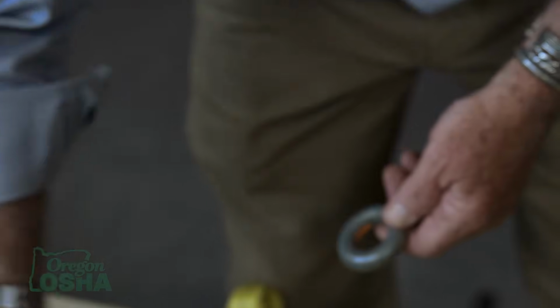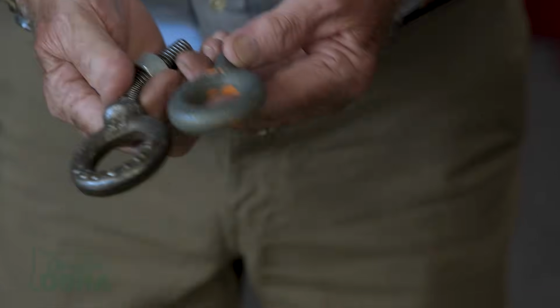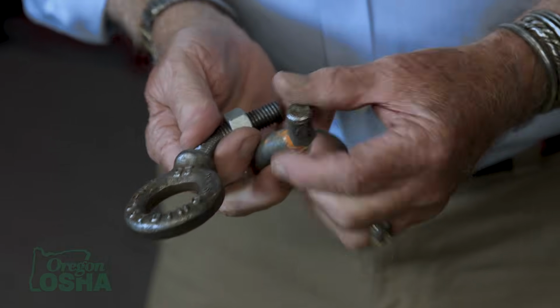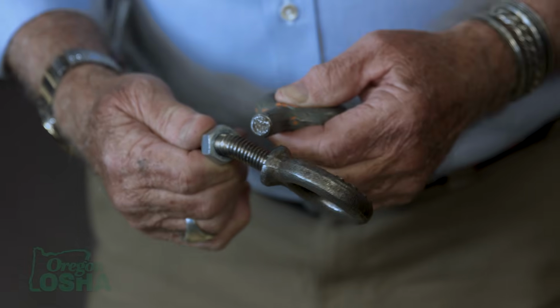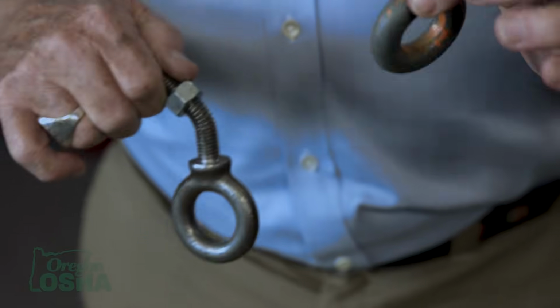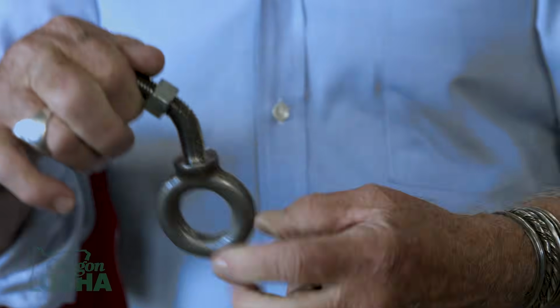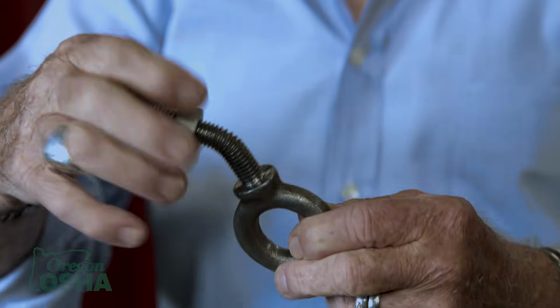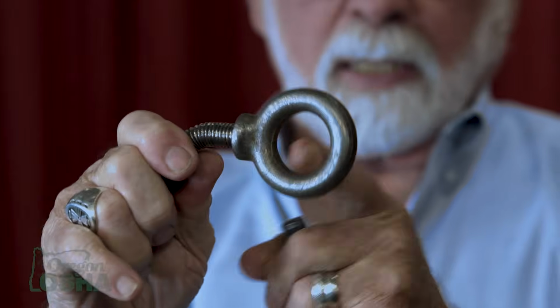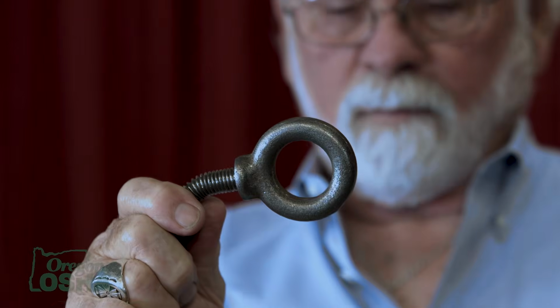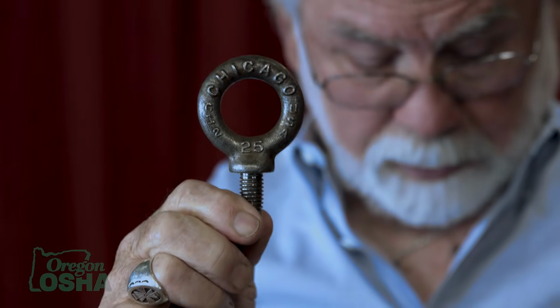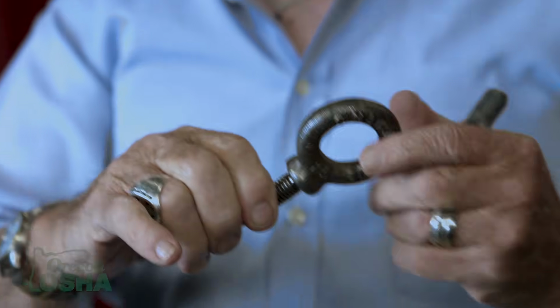Let's talk a moment about things we don't use. We don't use the bolts, and it's very obvious that something is wrong when you examine the material that's here, that this bolt may be rated, but it's rated only for a direct pull in line with the thread. You get this bolt 90 degrees and you pull it, it's worth about a third of what the unit is worth. These actually come off of a major site here in Oregon that were installed by somebody who knew they needed anchors but didn't understand the application of the bolt.